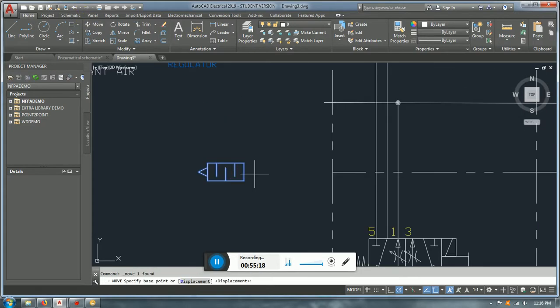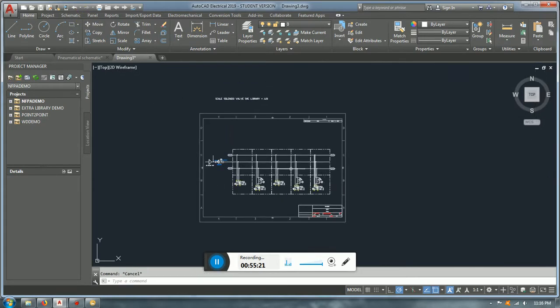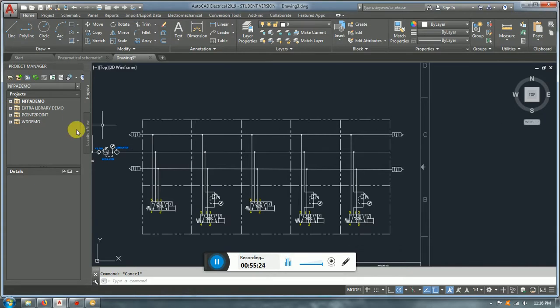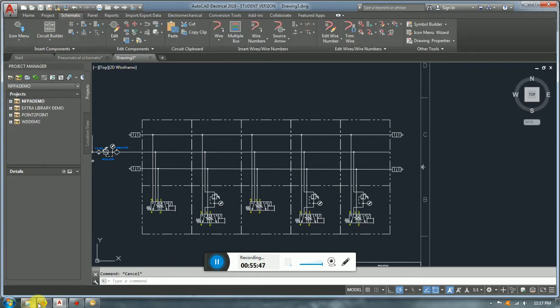Okay, typical manifold like that, you want to have both ways where the air comes and it leaves. You want the air to leave, to go to the atmosphere as fast as possible. This is a fast way, but at the same time, with that, you control the noise, which is annoying, I can tell you. What about the main one? The main one is where the air comes in, but you don't want it to leave. So what you're gonna install is a plug. Okay, what is a plug? It's just like a threaded plug that you put there with some Teflon tape or Teflon paste or something, so the air doesn't leak through.